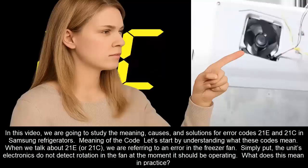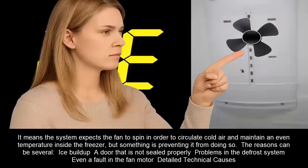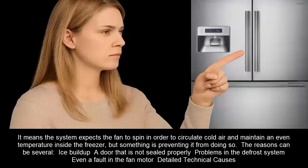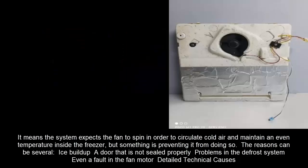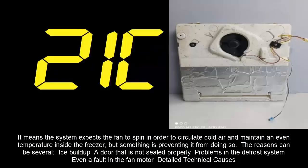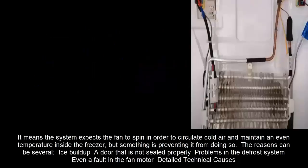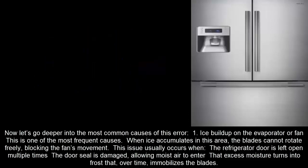What does this mean in practice? It means the system expects the fan to spin in order to circulate cold air and maintain an even temperature inside the freezer, but something is preventing it from doing so. The reasons can be several. Ice buildup, a door that is not sealed properly, problems in the defrost system, even a fault in the fan motor. Detailed technical causes. Now let's go deeper into the most common causes of this error.